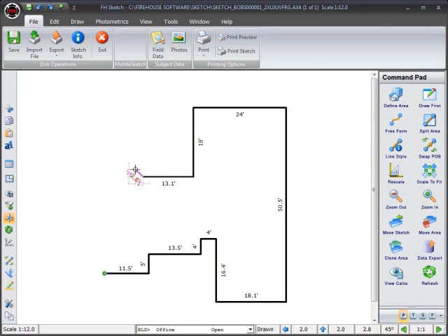Before we anchor the line, there are a couple of on-screen displays that will help you verify the accuracy of the lines and areas you draw. First, as you drew the second measurement of the angle, Rise and Run dimensions appear, offering instant feedback. You'll also find similar information in the lower right-hand portion of the interface. This area that we refer to as the tracking port provides real-time feedback of the current line drawn by reporting the rise and run as well as the total length of the line and angle. Just remember that before you anchor your line, take a glance at this information provided for quick verification. Let's anchor the line and dimension by pressing Enter twice and continue with the office area. The face of the bay window is 6 feet to the left.